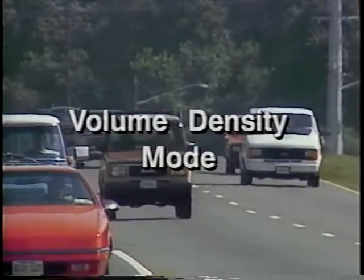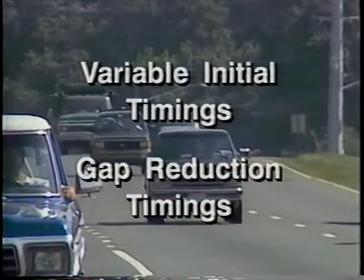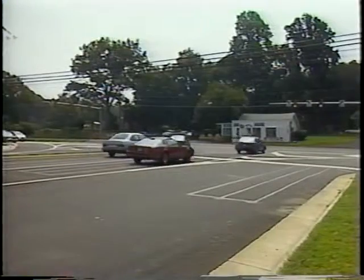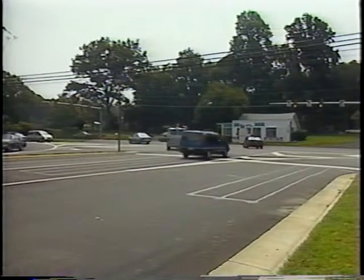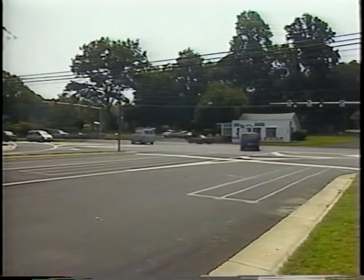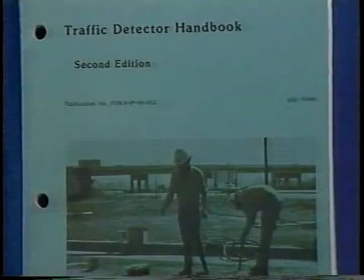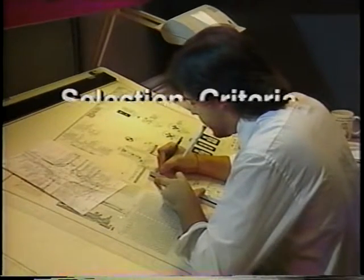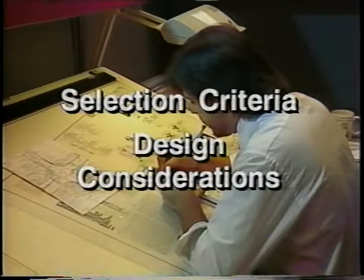This type of actuated operation offers variable initial timings and gap reduction timings to accommodate the increased traffic. These additional timing parameters take into account the waiting vehicles behind the first one in line, as well as the wait time of the vehicles on a conflicting phase. Consult your handbook for further design possibilities. During this presentation, we have discussed the selection criteria of detector design as well as the design considerations.